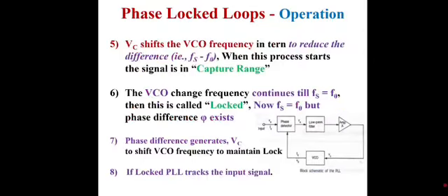The phase detector produces both the sum and difference frequencies. The LPF removes the high frequency sum component, and the difference signal, amplified, is applied to the VCO as the voltage control. Let's move on. Let's see what happens next in the locking process.